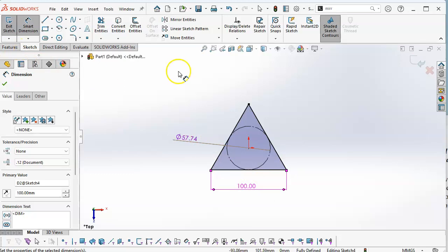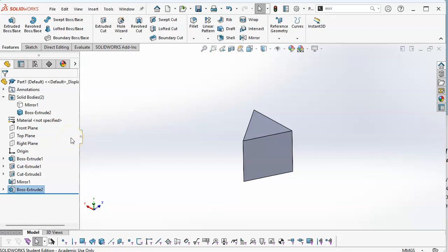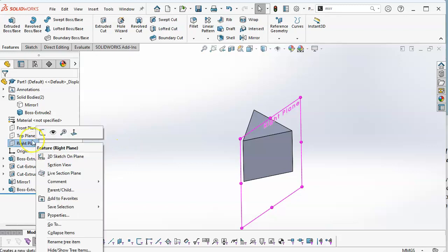All right, so let's see. I want to cut this along this direction, so I'm just kind of planning ahead for the right plane. We're going to extrude, and 100 millimeters should be okay. So when I cut this on the right plane, I'll be opening a sketch. Know that it's going through there, and just based on my geometry, I'm going to cut this way to get my shape. All right, so I'm opening up the sketch, and that was a right click.